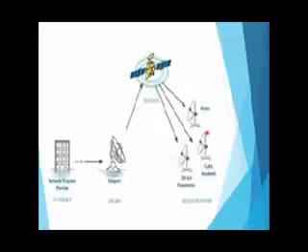With direct broadcast satellite, or DBS TV, the system is designed for consumer reception directly from the satellite. The new DBS system features digitally encoded video and audio signals, which makes transmission and reception more reliable and provides outstanding picture and sound quality. By using higher frequency microwaves, higher power satellite transponders, and very low noise GaAs FETs in the receivers, the customer's satellite dish can be made very small.